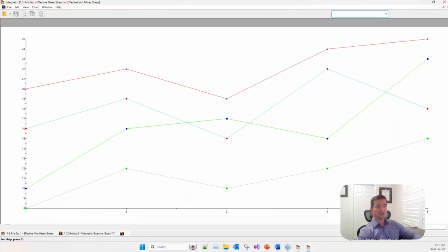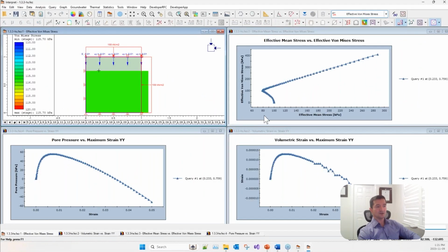Now we are looking at undrained behavior for this material. This is the effective stress path. So you have generation of excess pore water pressure, positive, then negative going up. This is pore water pressure generation, positive going down, negative. And there is a slight volumetric behavior change. It's very little, but that's because the material is now considered undrained and nearly incompressible.